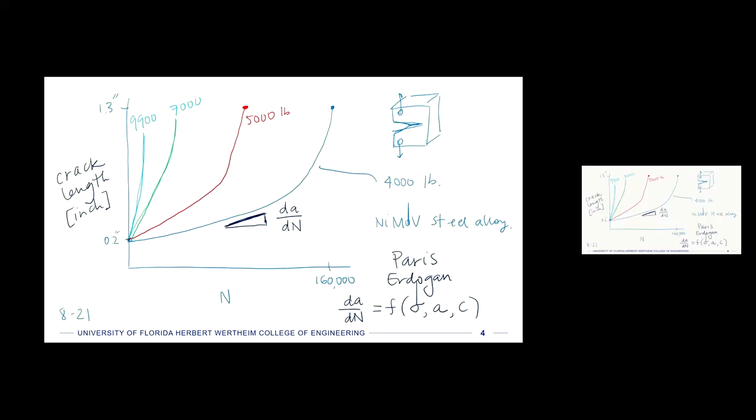So they noticed this and said, we sort of understand what's happening, but we don't know how to normalize this down in order to use it very well. So they looked at these factors and said, from linear elastic fracture mechanics, we already have expressions that relate the stress and the crack length to the fracture toughness. We had this expression where the critical fracture toughness was related to the stress times the square root of pi times the crack length.